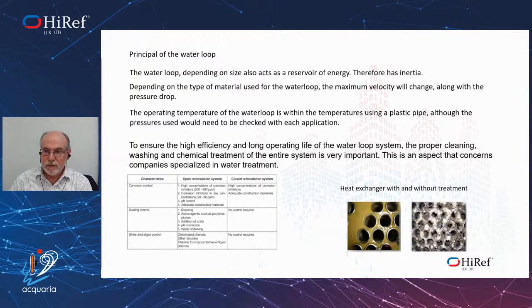The other area to consider is when these have been operating for 10, 15 years, the cleanliness of the pipe internally needs to be considered. How is the water treated? How is the system operating? Otherwise, you can get algae and slime buildup, which, in the heat exchangers, especially on small apartments and residential equipment, as well as the retail, you can get blockages within those plate heat exchangers, and they need to be flushed out.